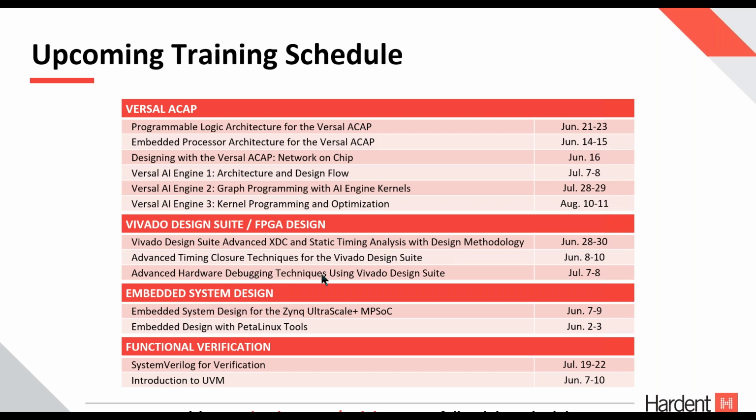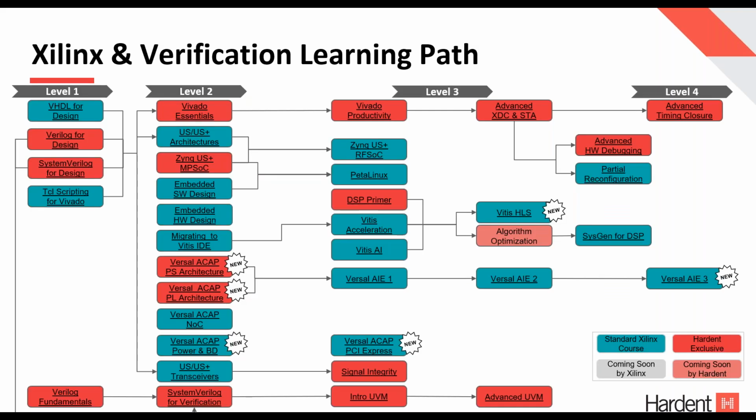And I talked about it earlier, the hardware debugging techniques where you can actually target hardware residing in Montreal to use ChipScope Pro or Vivado Logic Analyzer and help characterize your gigabit transceivers and characterize the paths of those using hardware as well, using the Serial I/O toolkit. We do a lot of embedded design, and functional verification is a path that is really necessary as we get deeper and deeper into FPGA design and UltraScale, UltraScale Plus, and now into Versal. That functional verification is just critical to making sure that we're advancing properly.